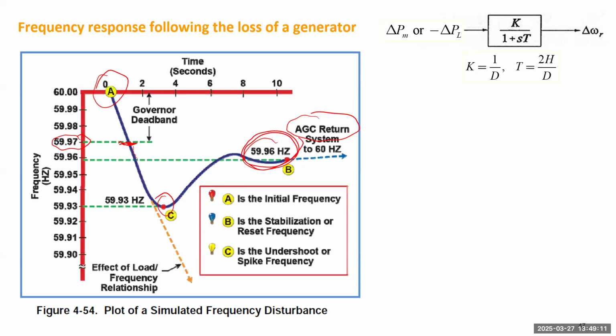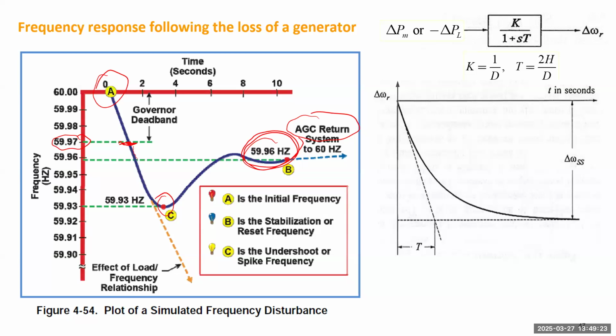If we model the total generation of the system through a total inertia constant H and the total frequency dependent load D here, we already solved that the frequency will decline following this relationship. If there's no frequency dependent load, this is almost like a straight line. But with frequency dependent load, it will finally stop at some largest frequency deviation, but that can be huge, right? It can be much higher than any threshold we can allow the frequency to operate.